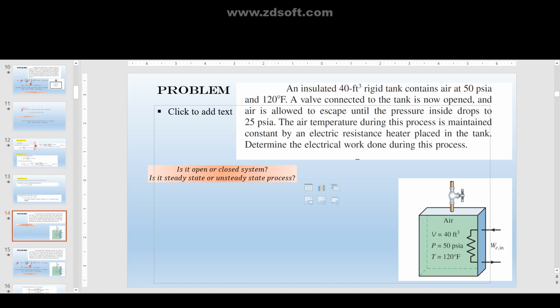So keep in your mind that you have the temperature. Correct. The temperature is 580 Rankine. So you have the temperature. You can use table A17, I think. Yeah, A17E to find the properties of air, as you know, ideal gas. So you can find the T1, actually this is the TE but not the TI, guys. This is a typo. So the TE, you have the HE, T1, T2, U1, and U2. Look, guys, temperature is constant.